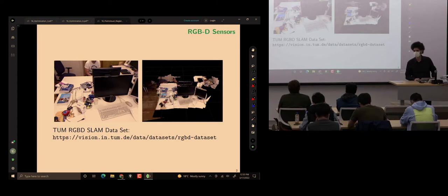In practice, there are missing values, there are noisy values. These cameras are very good for indoors. There are a few instances for outdoors, but their range is limited to usually 10 meters. In practice, maybe 5 or 6 meters. And illumination and sunlight can affect their performance significantly because they have to project light for sensing the depth. These are active sensors in terms of depth sensing.